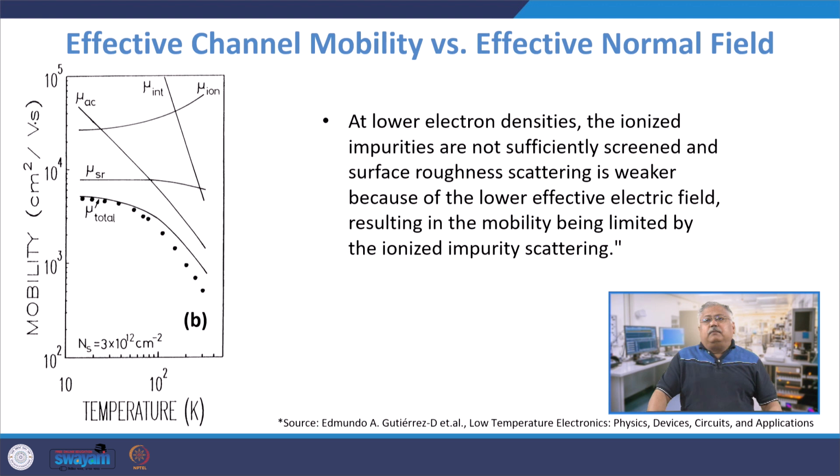One more thing which you should keep in mind, and this is important, is that as you make your gate voltage higher and higher and you are trying to invert the channel, you get something known as the screening effect. What is the meaning of screening effect? Screening effect means that the electric lines of force, rather than terminating in a particular charge, get screened by maybe a layer of charge particles, right? And therefore the effective electric field may not be the exact value which is being applied. That is more so the reason why, when we study mobility models, it changes drastically post inversion; this is possibly one of the reasons for that.